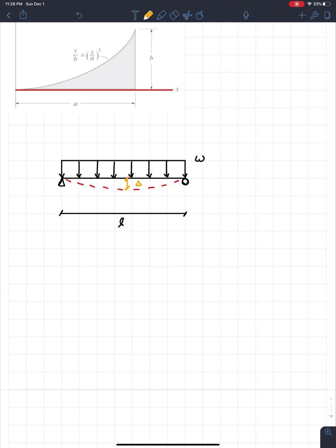When we're designing buildings, this deflection is very important because when we design things, we actually consider two things. The first one, as you guys may have guessed, is strength. So we obviously don't want a building to collapse or to fall. So the first thing that we do when we design a building, we make sure that the beams are strong enough to carry the loads. That's pretty obvious. But the second thing we check for is what we call serviceability, and that is to make sure that the deflections in all the beams are really small.